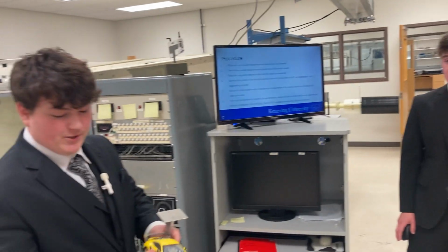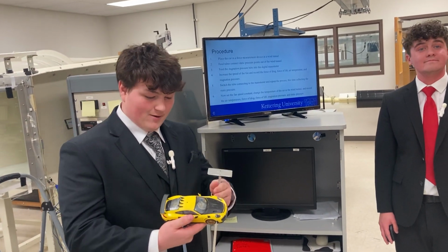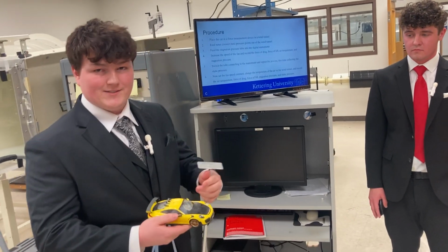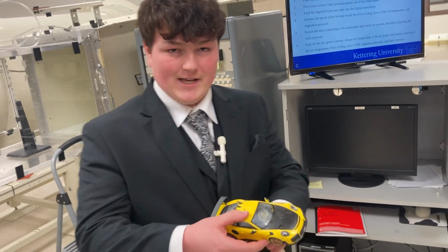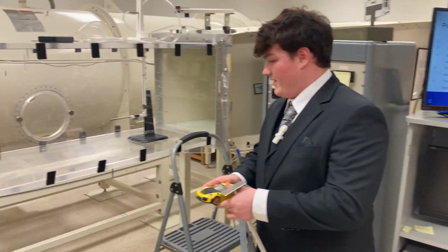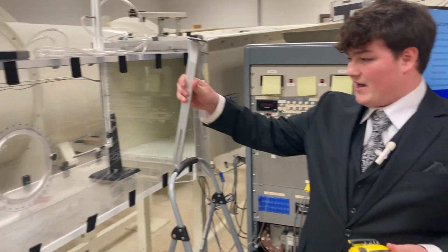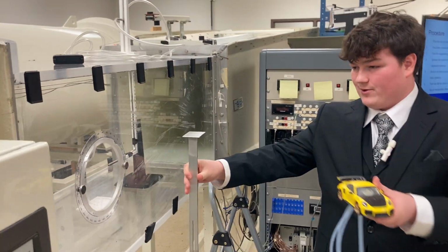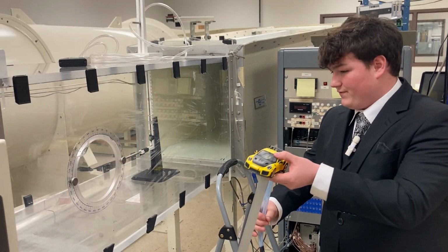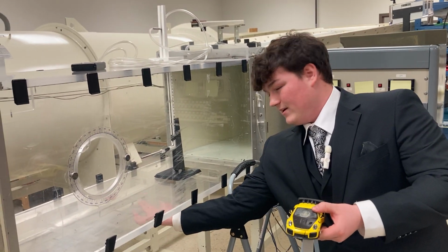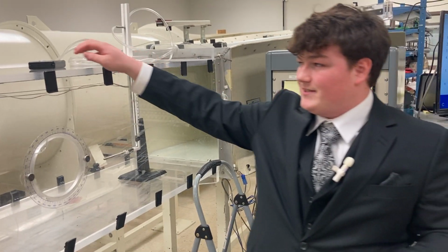So the procedure that we were following, to start, we had to get our model car all set up, drilling holes, as he said, and then actually mounting it onto our stand, which we had a different table under here. We would slide our car on the mount down, and it would hold it in a steady position. After that, we had to feed our tubes into a hole that was at the bottom for our readings with the digital manometer.